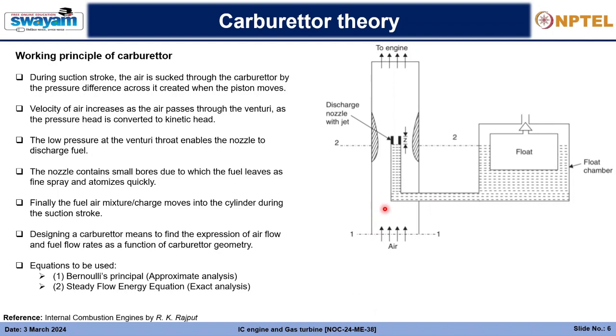So if heat energy is given to the air, it will expand, and that's why we need the steady flow energy equation. If no heat is supplied to the air, or the air does not get heated up, we will simply follow Bernoulli's principle. But none of this will affect the expression of fuel flow rate, and we will see that in the subsequent slides.